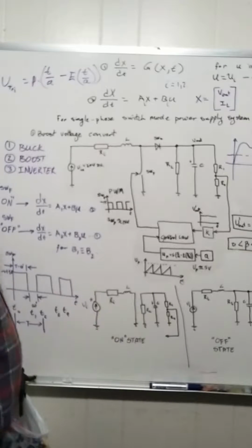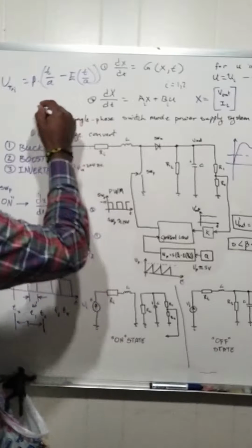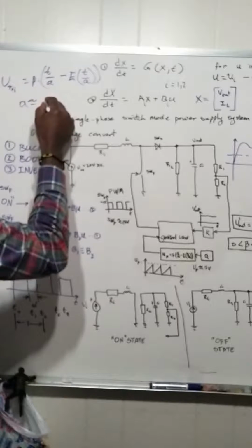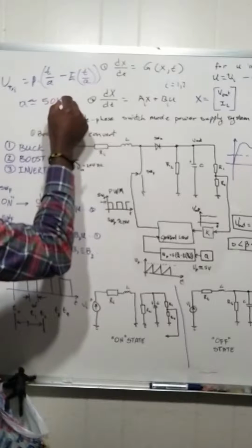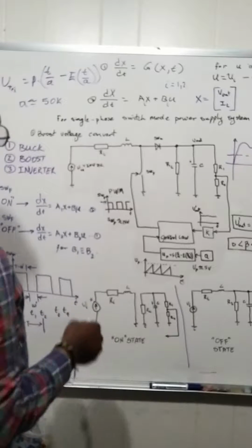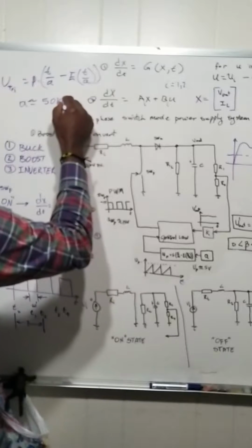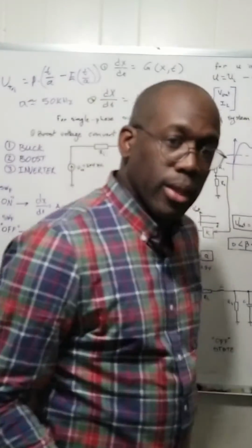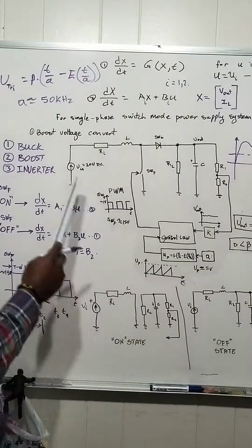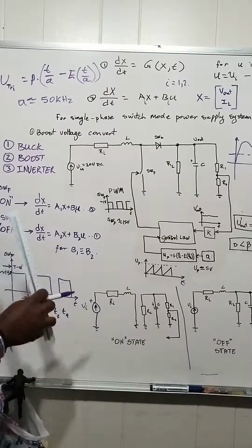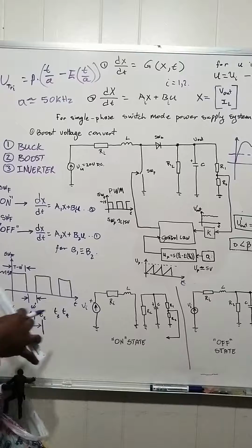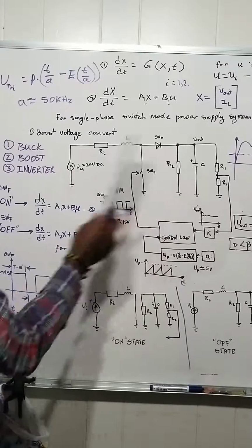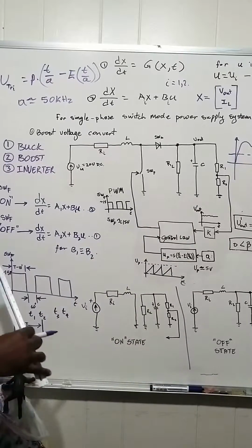I recommend, for even some of you students, always go for at least 50K. Okay, that's basically 50K. That's the frequency, right? 50K. That will allow the switch here to switch as rapidly as possible, to allow energy to be stored in the inductor, transferred to the capacitor, the filter capacitor itself, which is the energy storage.